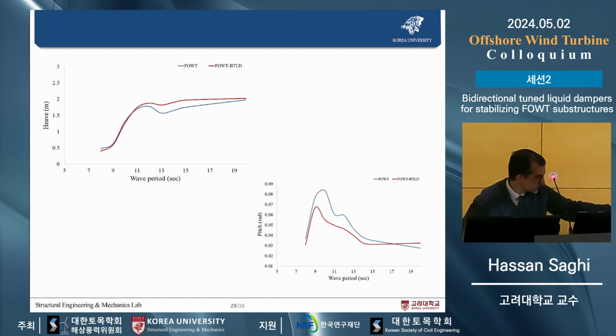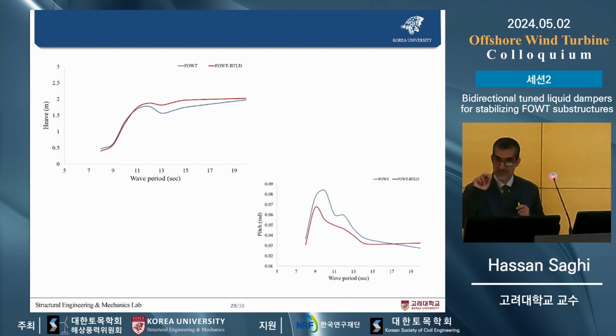However, for wave periods more than around 16 seconds, the suggested system not only fails to decrease the pitch motion, it increases the pitch motion for very long wave periods. You can see from this point, the pitch motion is more. And also for the heave, unfortunately, the suggested system cannot mitigate. However, our final goal was the pitch motion.